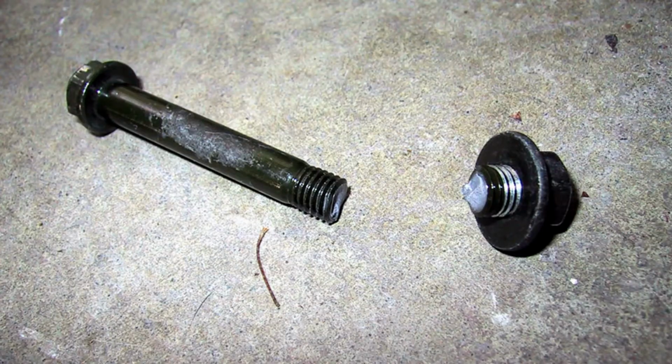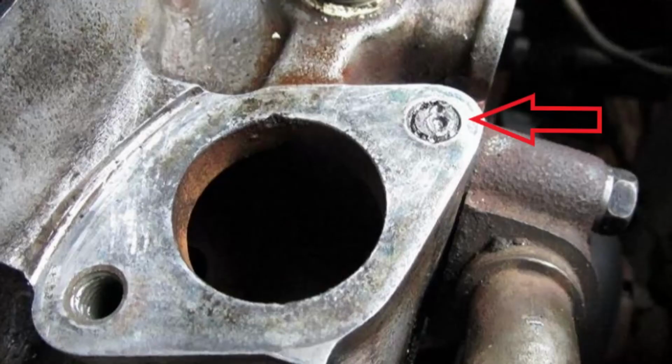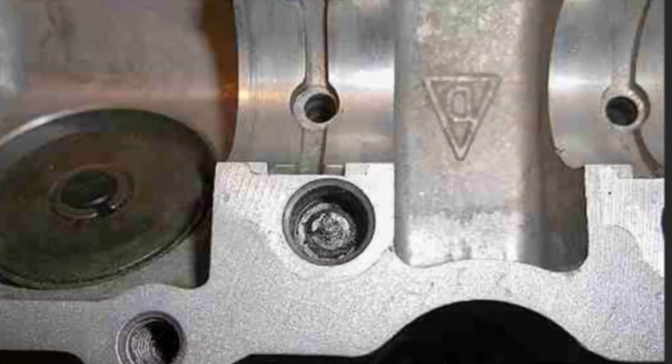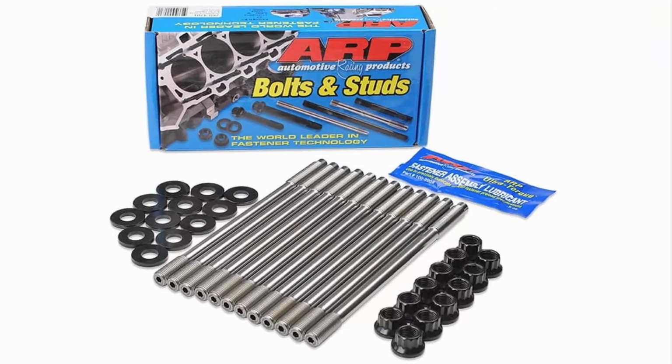And every time you reuse those kind of bolts, the risk of failure increases. A loose or snapped bolt isn't fun in any situation, and when it's your fault, it's that much more salt on the wound. So I suggest upgrading the head bolts/studs while you have it apart the first time. And this applies to all fasteners. You can usually feel or see when a fastener is at the end of its life. Don't put that rusty, stretched out bolt back in. Be patient and source something that has more life left in it. You'll thank yourself in the long run.